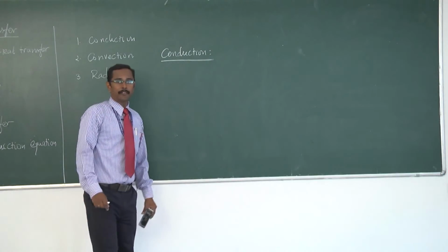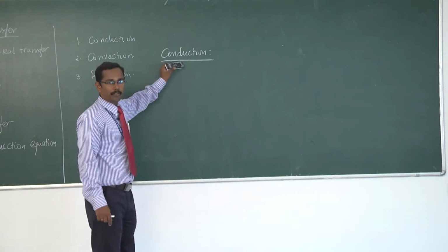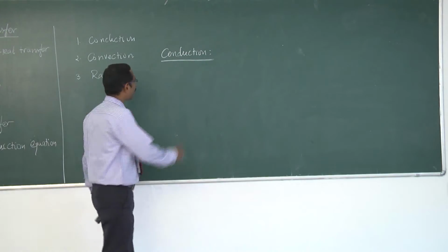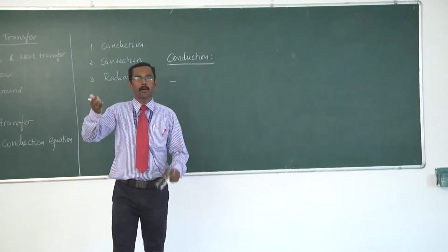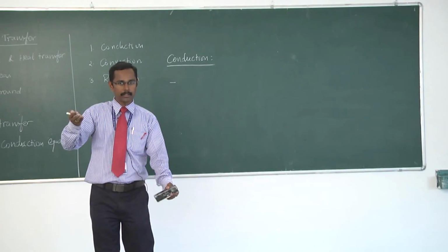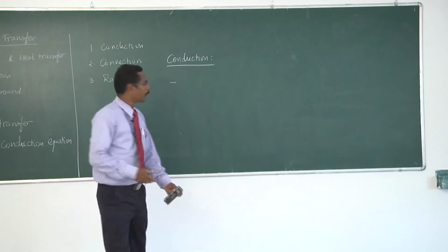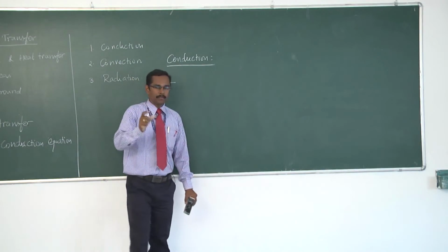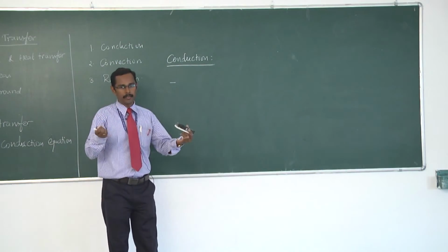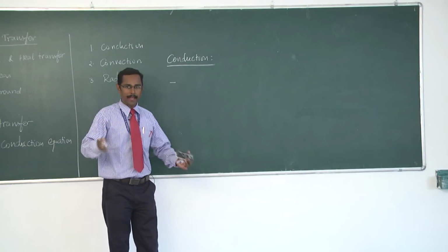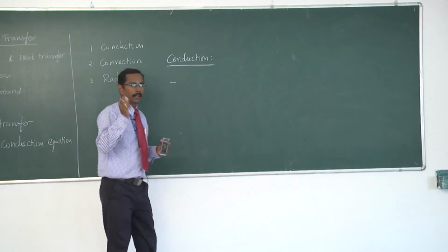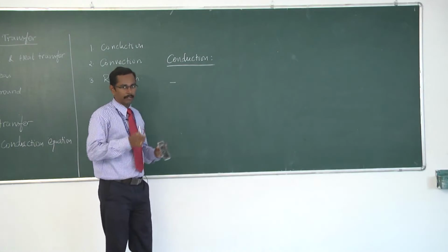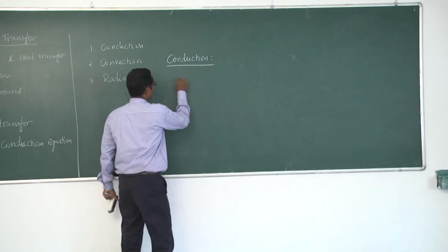Of the three modes of heat transfer, now I would like to focus on conduction heat transfer. In conduction heat transfer, the heat is transferred from higher energy molecules to lower energy molecules in the same substance. So, conduction heat transfer takes place in solids, liquids and gases. Now I would like to define the law behind conduction heat transfer, which is called Fourier's law.